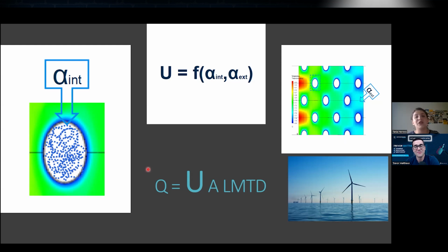But usually you also don't want to have a big heat load in your cold room, right? And it doesn't operate continuously 24/7. It's just short periods of time. Yeah. And that's important to understand. So when you're sizing a unit, I know we're a little off topic here, but this is all about that heat transfer, because you're saying if we have a really wet evaporator, we've got a lot of water on that coil, it's going to affect that heat transfer. Plus, we're going to blow that water on top of all the product. So we don't want that. And that will come into the sizing of that system, I'm assuming, and the temperature of the coil itself.